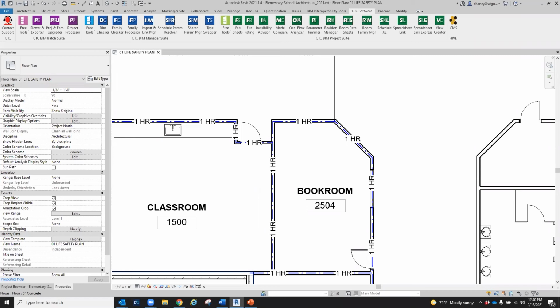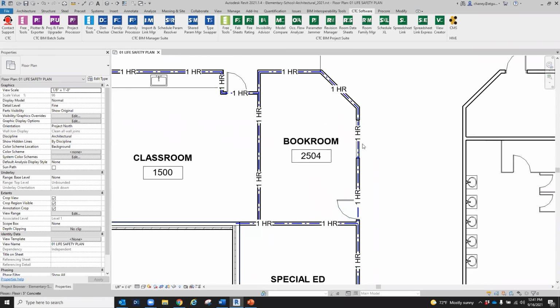So for example, columns, beams, floor decks, or mechanicals that pass through rated walls. If your objects are passing through rated walls, just like the door and the window, those lines will show up over those objects because that wall exists three-dimensionally, vertically, or maybe in a different view outside the view range, etc. That line will show up just like it does over these doors and windows.